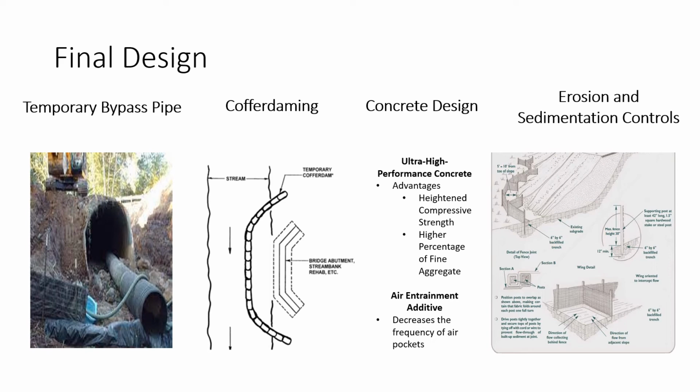The cofferdamming for this project will be sandbagging. So around each side of the culvert, there will be sandbagging set up to help protect the area that will need to be repaired with the concrete. Every day we will have to make sure that there are pumps placed into the existing cofferdam area to remove any of the water that piles up overnight.